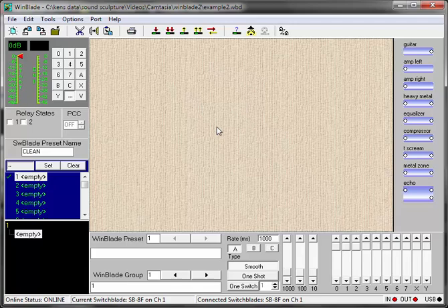Before we begin, check to see that the Fixed Gain button, indicated by dashes, is depressed and that the gain slider is set to 0 dB. This is to ensure that all the connections we make in our preset will have a fixed gain of 0 dB, which is the same gain as if you were connecting things together with just instrument cables. This is always a good starting point.